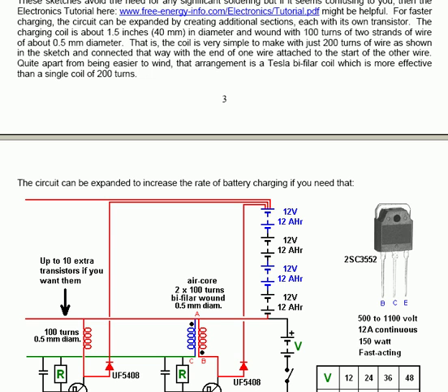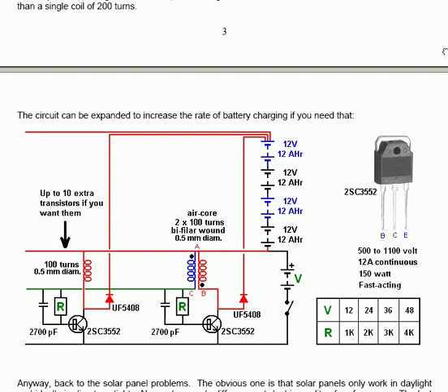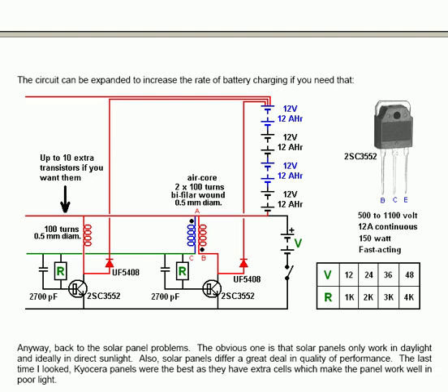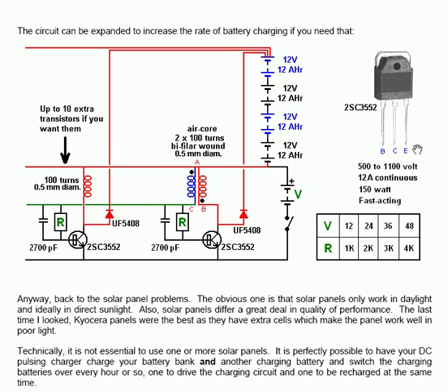You have, as before, your arrangement of driving battery, controlled charging resistor. For a 12 volt battery you are using a 1K resistor into the base of this transistor. 12 volts across 1K means that 12 milliamps flows through this particular resistor, or close to 12 milliamps.